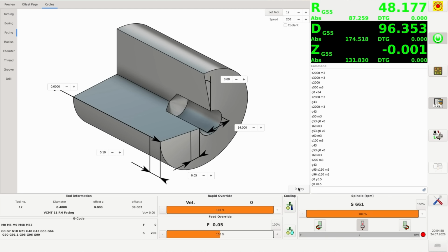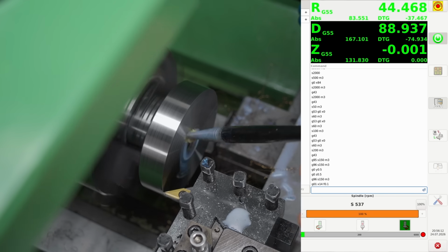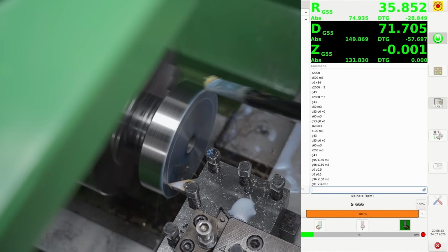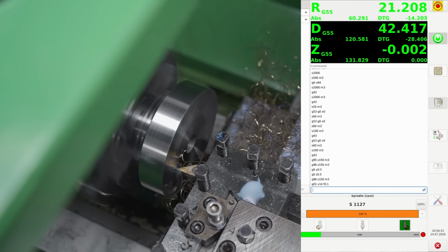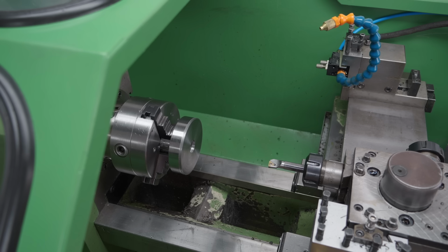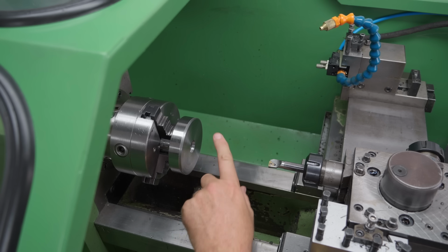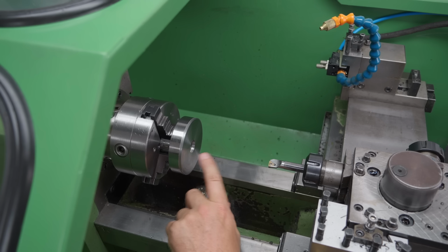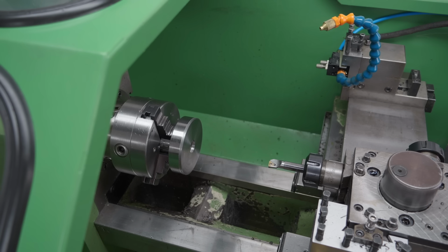So as you can see, it cut a taper of 1/10 of a millimeter rather than doing a constant 1/10 of a millimeter off the whole face. So I wonder if there's some sort of bug in the Lathe Macro, or it's just some sort of finger trouble from me. Anyway, I'll just do an MDI move to clean that up. Any recommendations on how to address this would be greatly appreciated, thanks. Right, now the damage has been turned off that face. Let's try this out and just make sure I haven't screwed anything up by running my same tool paths as I was using before to clean out the back of this thing.